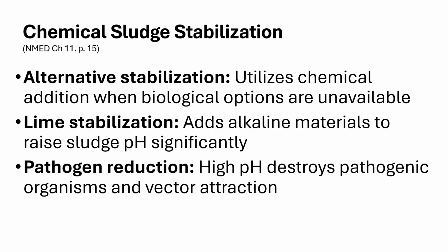Okay, we can also with these digesters use chemicals if we don't have an activated sludge plant. Let's say we've got a solids issue on a smaller plant, or we're managing solids. We're going to utilize chemicals like lime stabilization in order to stabilize the sludge if we don't have these microbes or the equipment to manage this biological process.